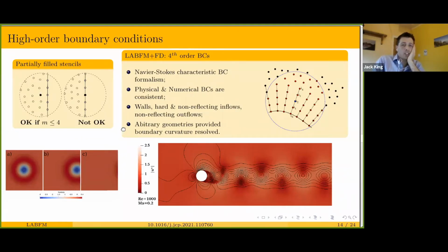Another nice benefit of these boundary conditions is that we don't have the additional computational and memory overheads of storing an extra set of ghost or mirror or dummy nodes or particles, as we often have to in SPH. So this boundary framework is quite attractive because it doesn't increase the cost by having these extra nodes.